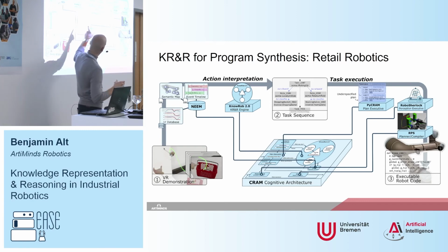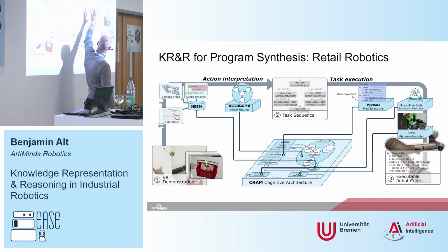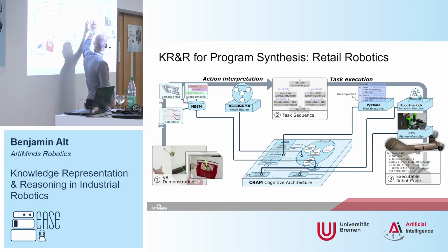And then when we map back down here to the task execution, we can have rules in place where we say, okay, we know that for a robot to insert a thing onto a flexible hook, that is such a stochastic process because of all this flexibility, we need to search for, in this case, the tip feature, right? We have feature abstraction, and we know that to insert something, we need to know where the tip of the thing is that you want to insert on. And if there's uncertainty there, we have to search. So we add the search motion.